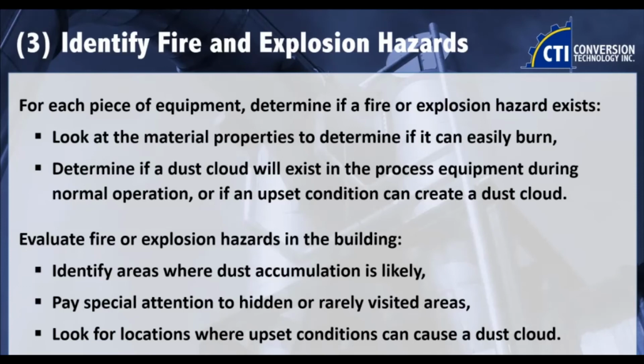Are you looking at a bulk bag unloading station that maybe even has dust collection on it? You're like, well, that's a closed system pretty much, so there's no issue. But there is an issue around that station, in that if that bulk bag drops off the hoist, you can get a dispersion of powder in the air. So that would be an upset condition.